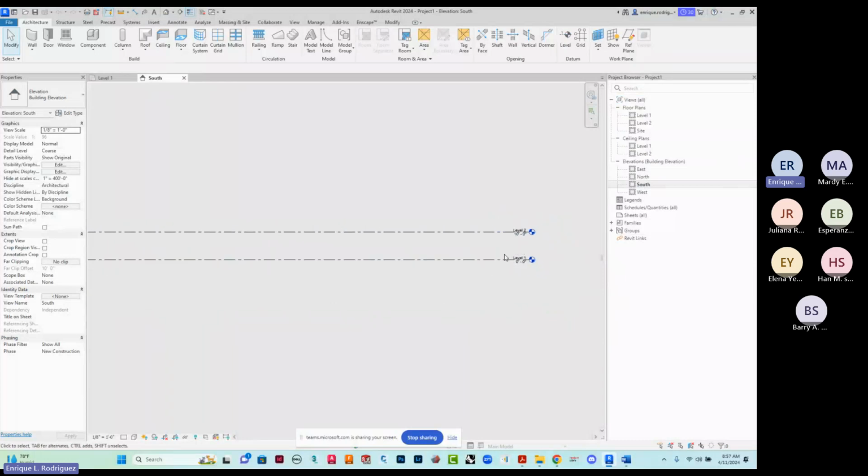Now, if we need to create a third level, which we will, it is going to be the top of the plate of the walls for the second floor. So when we create the second floor, we're going to put the top of wall elevation as one of our levels, which is going to be the bearing point for the trusses and or rafters that are on there. We may have some subsequent levels after that for maybe top of beam for the porch beam that goes around. We also may have a top of porch elevation later on, but at this point, we really don't need to do that. So how do we create a new level?